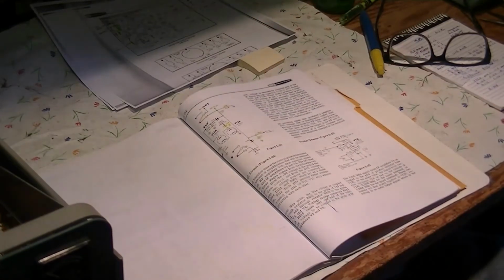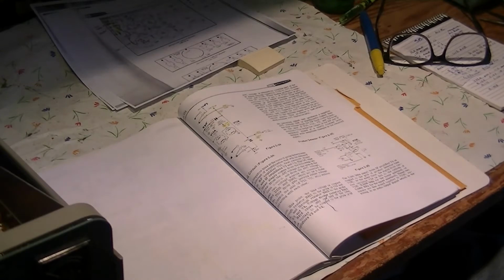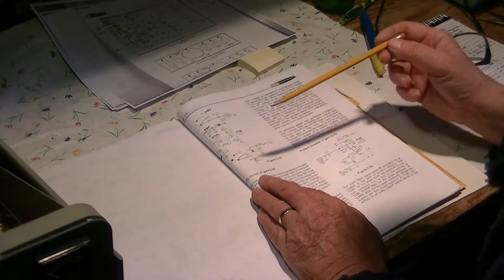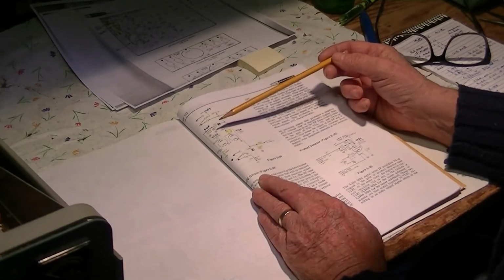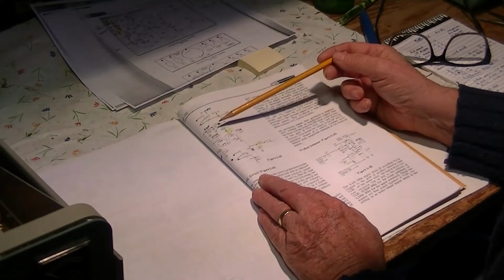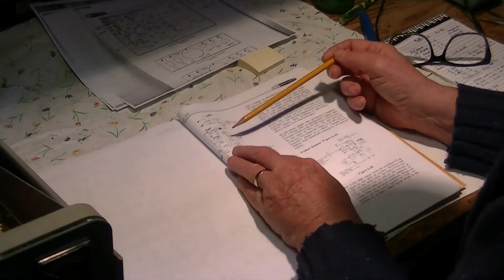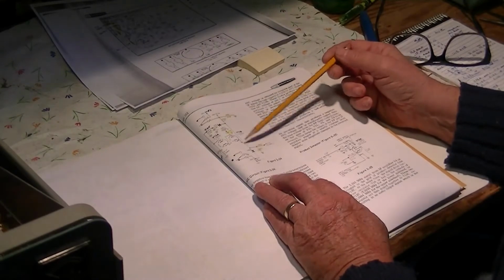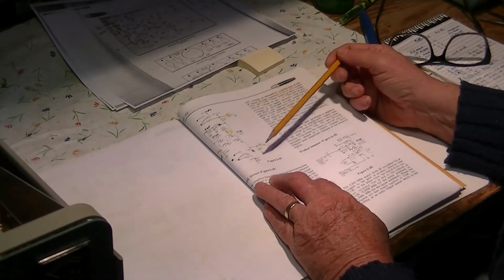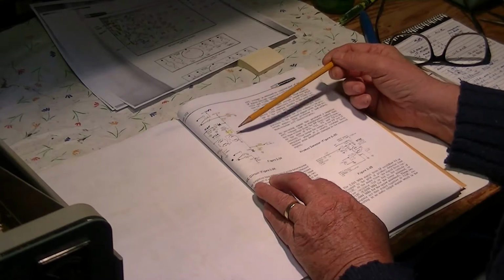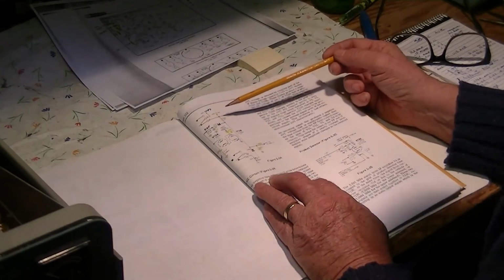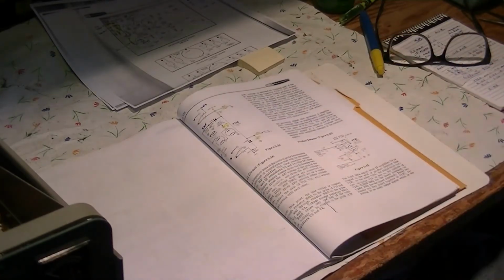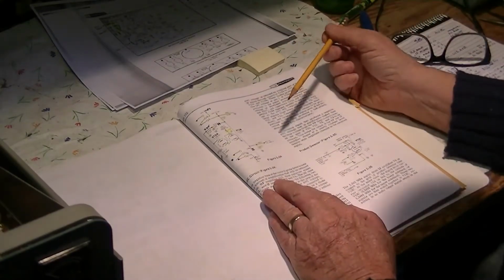The AVC circuit, this will tell you, is composed of negative bias that comes off of the RF gain control, combined with variable negative bias that comes from this AVC rectifier. And there's two diodes that act as gates that allow these two voltages to combine without interacting with each other, so that the voltages don't go backwards.